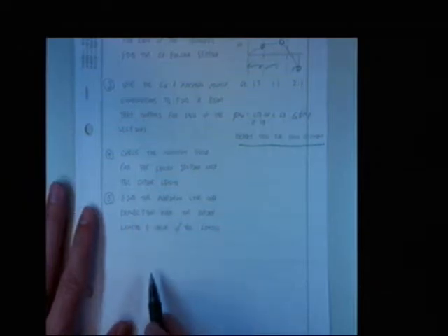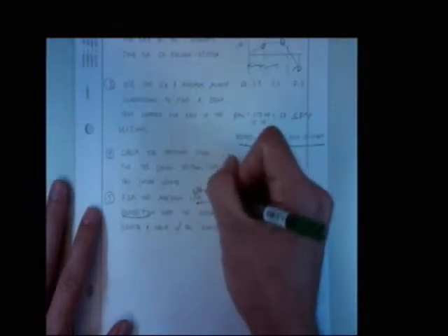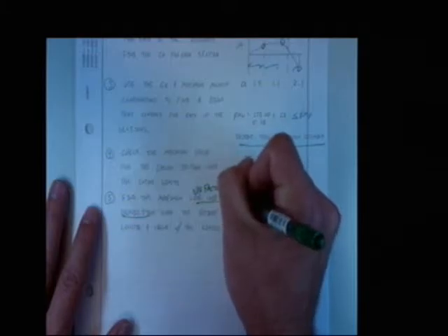Check the maximum shear for the chosen section over the entire length. Find the maximum live load deflection over the entire length and check the limits. Hey, live load deflection is unfactored. Don't forget, unfactored. That's just a nice summary, I think, of what we talked about before.